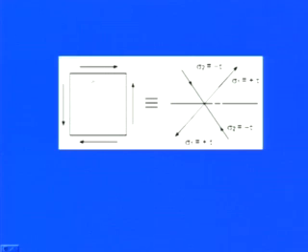We have a uniform structure, the shear stresses are applied at these two corners, and we have the complementary shear stresses just to maintain the balance of this particular element. So now this element is perfectly balanced under the application of pure shear. If I want to replace those things, what I need to do is just apply the direct stresses at 45.